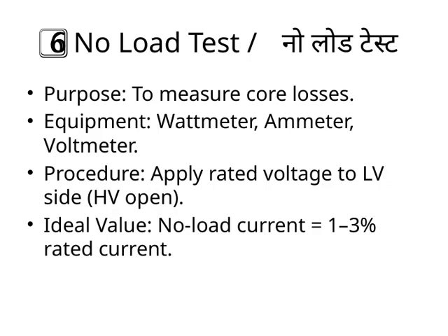Let's talk about the no-load test, known in Hindi as no-load test. The main purpose of this test is to measure the core losses in the transformer. To do this, we use some basic equipment such as a wattmeter, an ammeter, and a voltmeter.